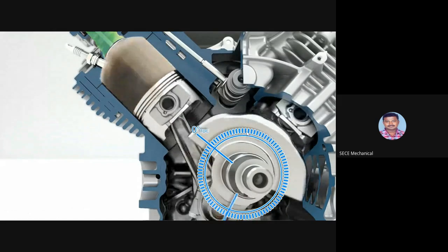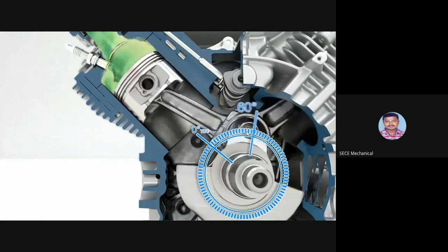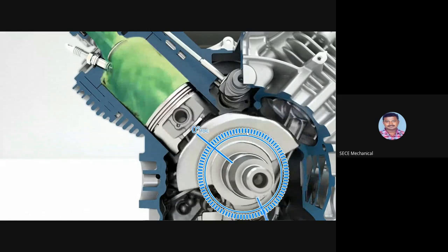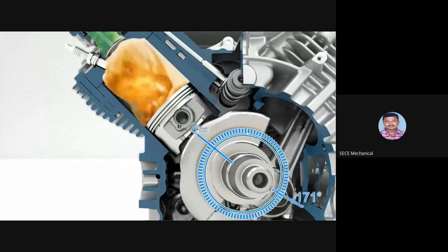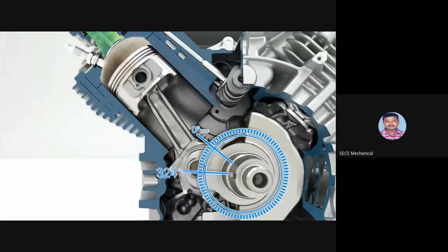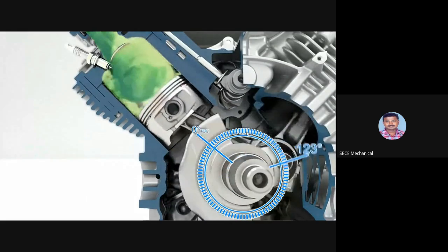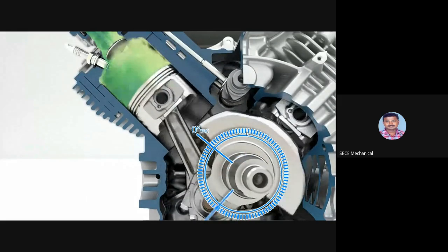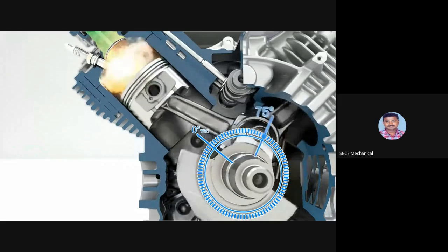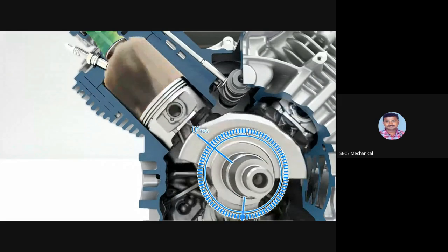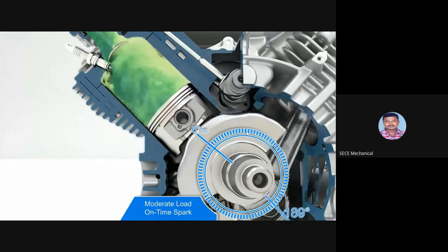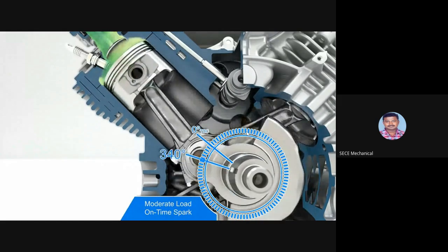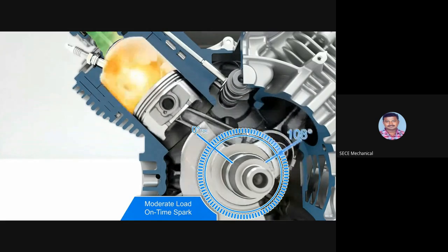Four-stroke engines require 2 full turns of the crankshaft, or 720 degrees of rotation, to complete one full cycle for an individual cylinder. If we look at the spark events during various operation modes, we can see the difference of when the spark occurs relative to engine rotation degrees. Let's look at some varying operating condition examples. When the engine is operating under moderate load and high-speed conditions, the proper spark advance will be delivered at 340 degrees, or 20 degrees before top dead center.